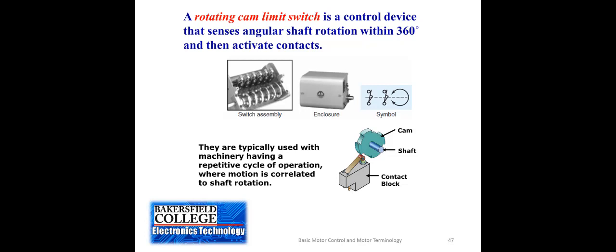Before we had automatic controllers, computer-based controllers, microprocessor-based controllers, we could have timers that had cams in them, and limit switches that followed those cams. So as it rotated, certain switches would close and certain ones would open. The symbol for that type of timing switch, a rotating cam timer, is shown up here.